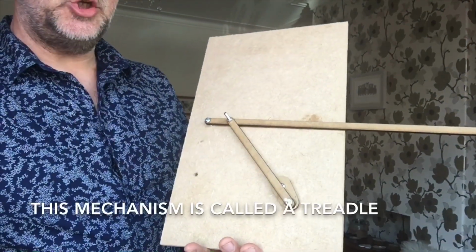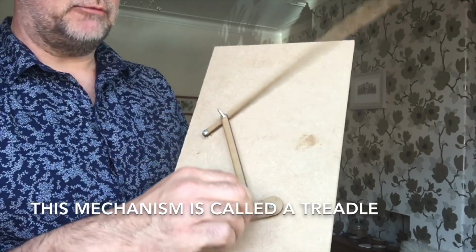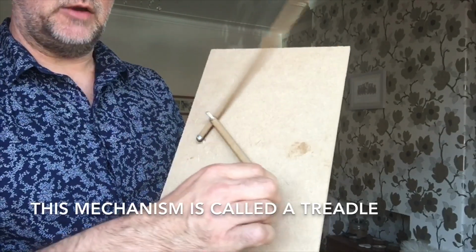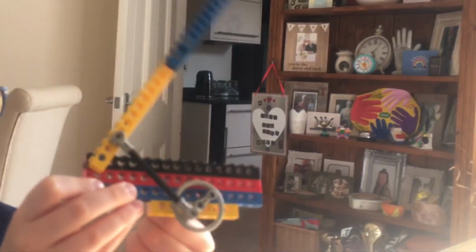Another mechanism here that uses a crank, you've got the crank there, you've got a connecting rod here, you've got this linkage here that's fixed to the board at that end. When you turn the crank round, you get that kind of motion, which is what's used in quite a lot of windscreen wipers. And because it's a complicated mechanism, I had to model it in Lego first. This is something you should consider doing in your projects.